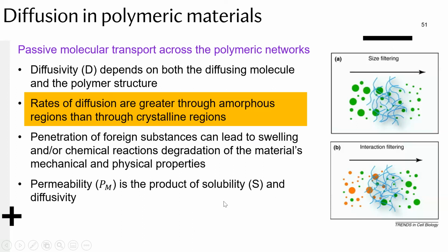Now, solubility means how much of these molecules can actually get in and mix within, or in other words, the limit to how much oxygen or CO2 or whatever molecule content there can be at the same time inside this mesh. Now, if this material is insoluble, even if it can diffuse fast, it can't even get in there, okay? So imagine two materials that have different phases and they can't mix, right? It doesn't matter if those molecules can actually pass pretty fast, they can't even get in there.